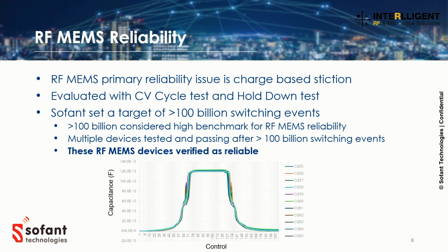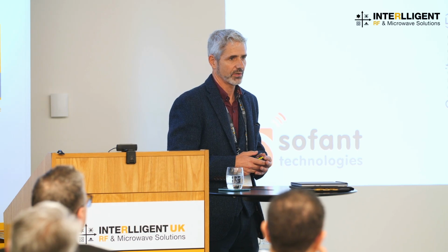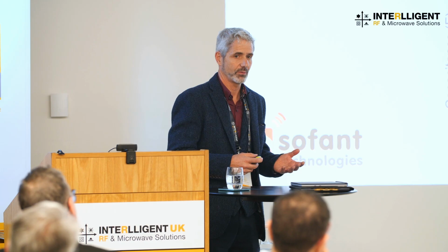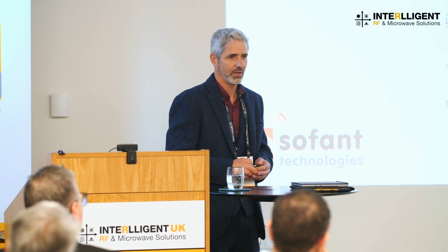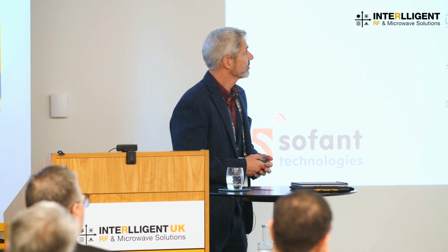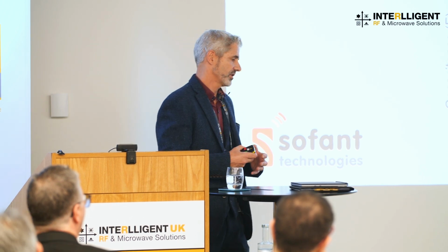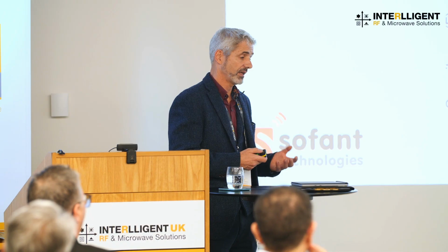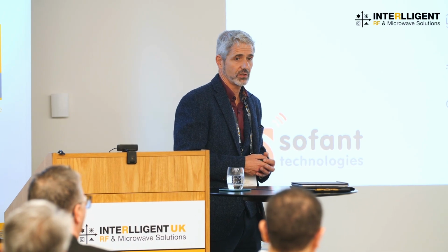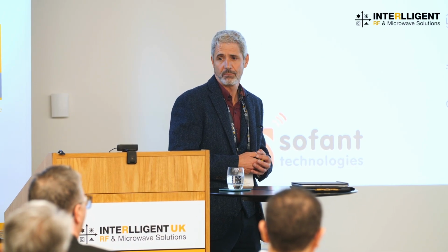I mentioned MEMS before. I mentioned reliability. So just to pause on reliability, because we find there are lots of people who are skeptical about RF MEMS and how you make it reliable. Traditionally, the structure of MEMS that we use is a capacitive MEMS. Charge-based stiction is traditionally the stumbling block.